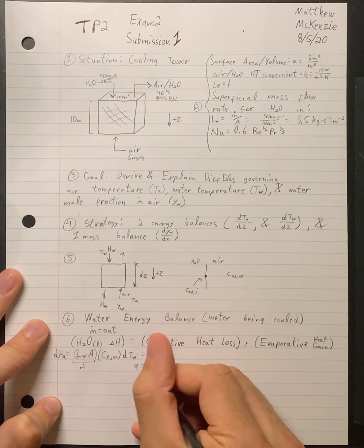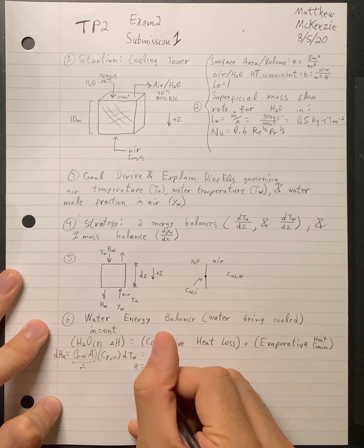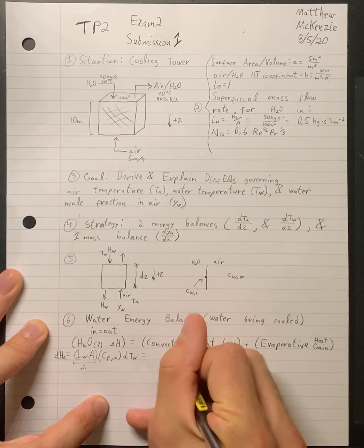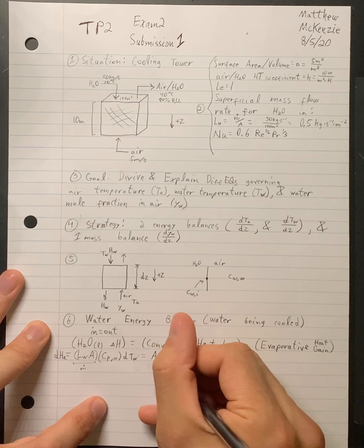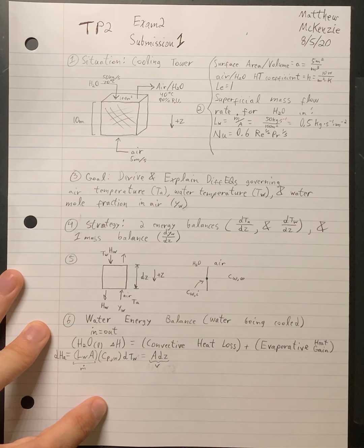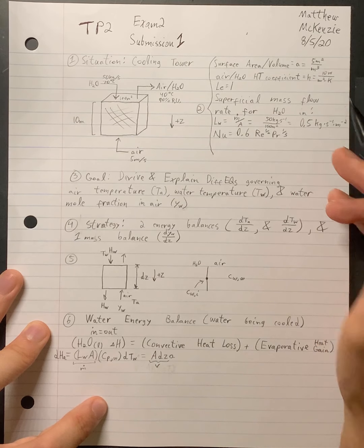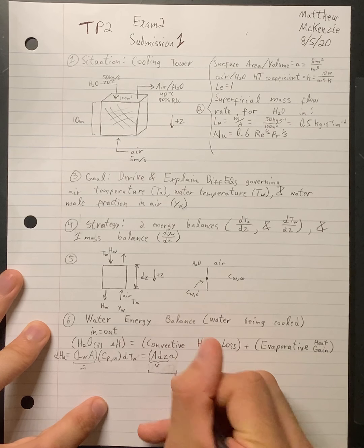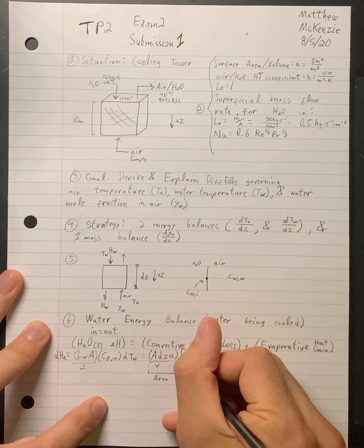Recall, we're basically writing out something very similar to one of the heat equations where we've got Q equals H times delta T. We're going to be writing out Q, A, H, delta T. We first got to write out our area component. What's this area component look like? So the first thing we've got is some kind of volume here, which is A times dz. This guy is basically just a differential volume in another sense. You can multiply that by the ratio of surface area to volume, which gives us the surface area that we're working with here. So this guy, in a sense, is our area for transferred materials.